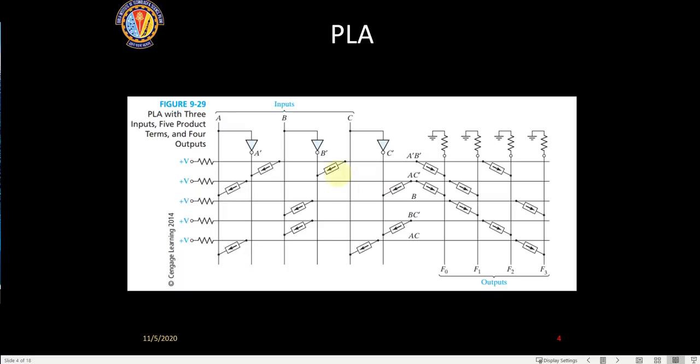All right, thank you. So it is slightly different from the ROM we studied. This is known as the AND gate programming. When we write a program, there will be certain fuses like this, or diodes, and as per our program, wherever we want, it will get programmed. There will be software where we define wherever we need these connections. How these connections are made, we studied in the last class.